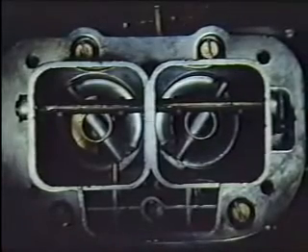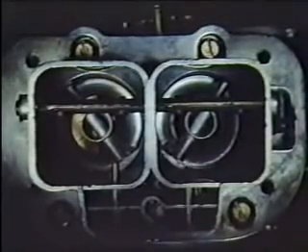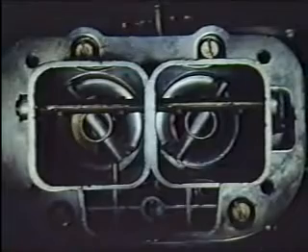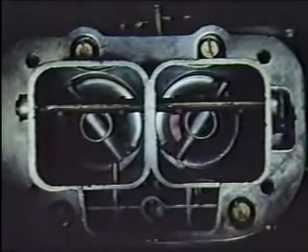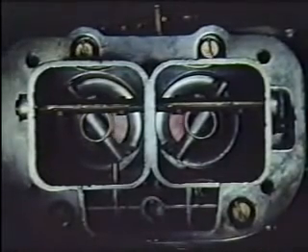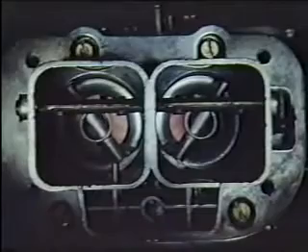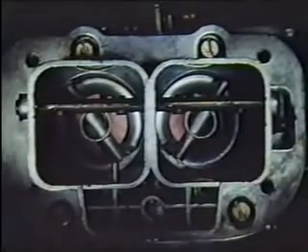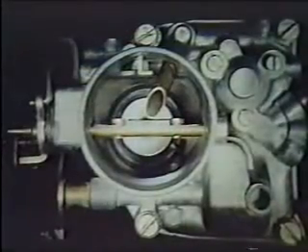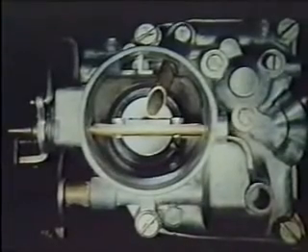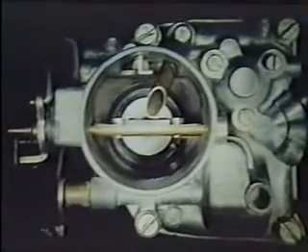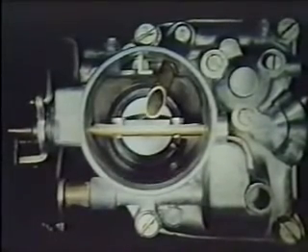At lower revolutions, the needs of the engine are met by the smaller carburetor. At higher revolutions, the larger diameter carburetor comes into operation, greatly increasing the flow of mixture into the engine and improving its performance. The task is always the same. It is simply to deliver the right mixture of fuel and air to the engine at precisely the right moment.